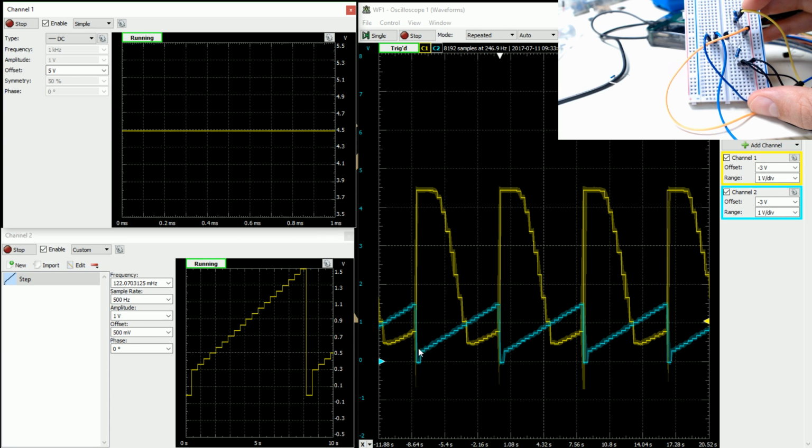Okay, so this is a little bit lower than I thought. This is starting at 0.3 volts or so. So right about here it starts to turn on, right? So 0.6, 0.7. The transistor, the VBE, is creating current in the base, from base to emitter, and then it's turning on current from C to E, and then what we're seeing is this voltage represents the drop across this resistor here, right? We're just looking at it backwards.